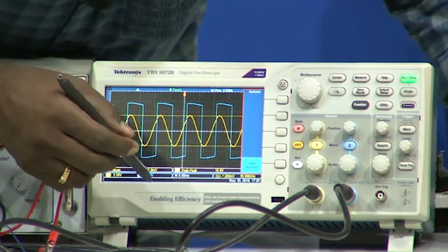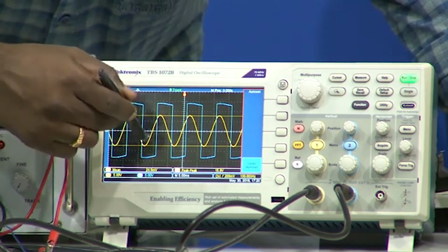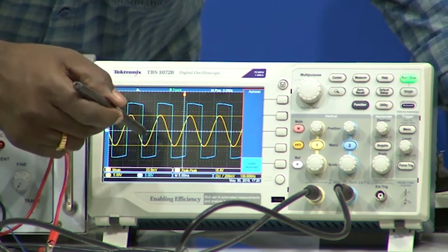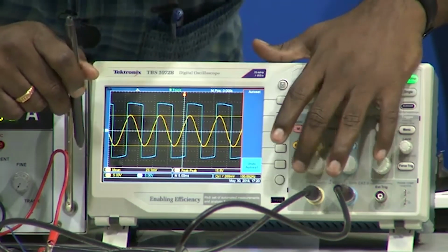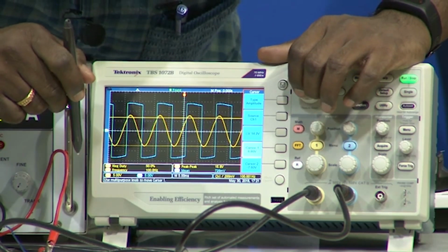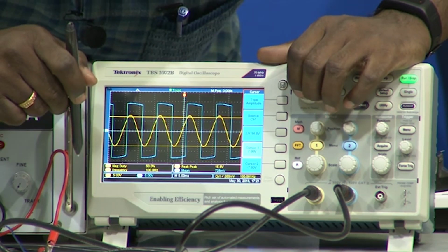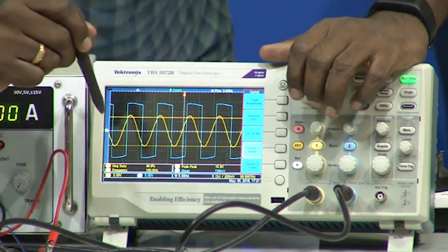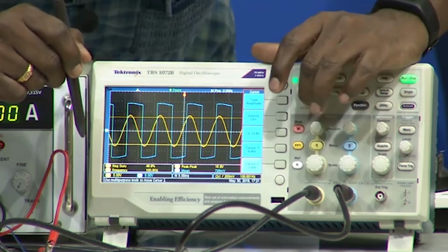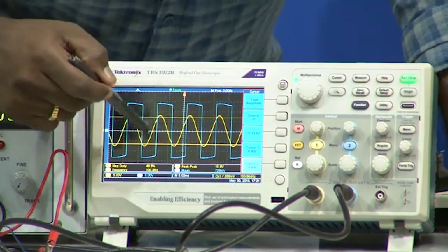Now, what we are doing is, we will place the cursors, both the higher threshold cursor and the lower threshold cursor, at their respective places. In this case, the value is 6.8. So, I will see whether I can exactly place it at 6.8, if not, approximately near that value. Yes, this is, yeah, okay, 6.8, right. Again, I will make the lower cursor also at minus 6.8, right. So, both the higher cursor and lower cursor are set.